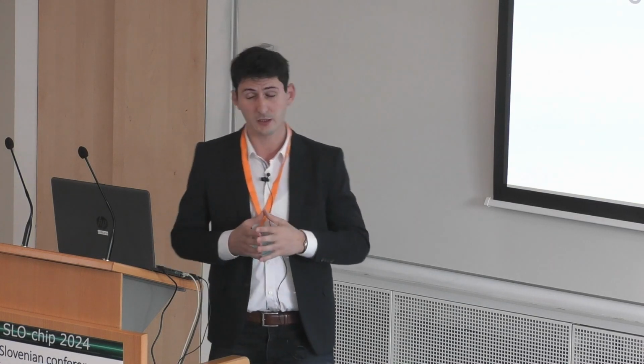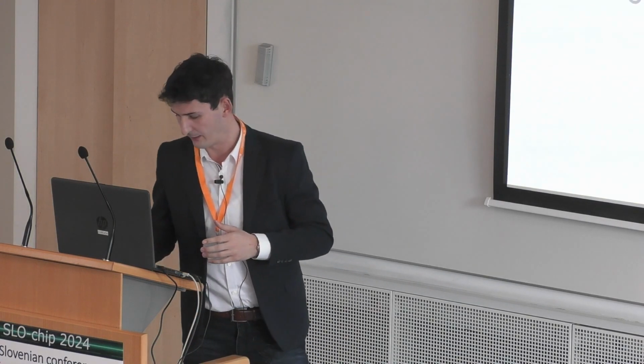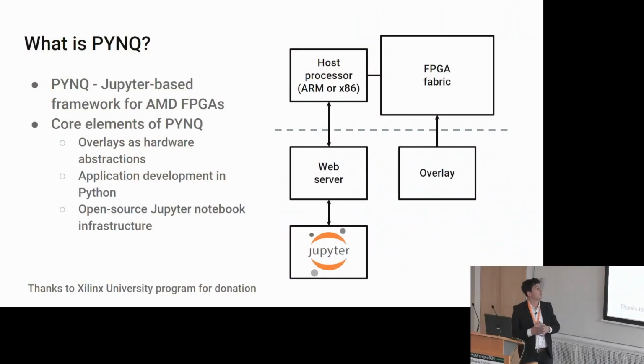I want to, on behalf of Nejc, share our experience with PYNQ for accelerating FPGA application development. What is PYNQ? PYNQ represents a Jupyter-based framework for developing applications targeted for FPGAs. The core elements of PYNQ are overlays as hardware abstraction.